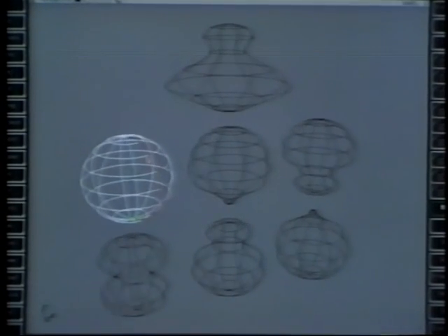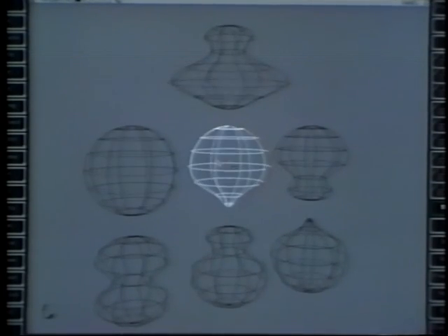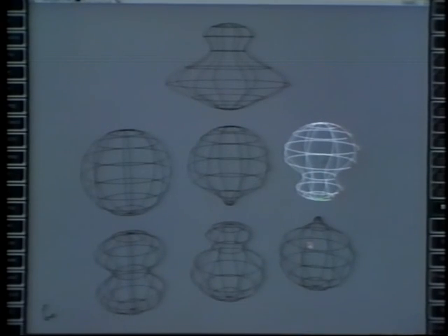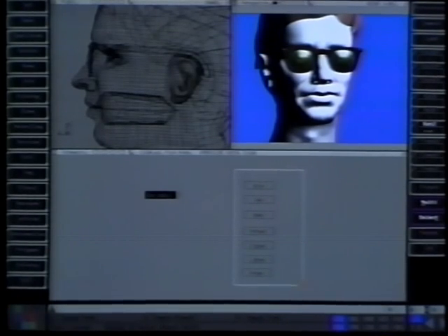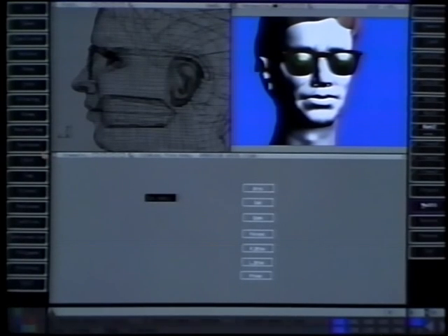It was okay for me to demonstrate Select Key Shape by laying out all the target shapes in different places on the screen, because the shapes in the shape list only record the position of each point relative to the object's center. In a real production, however, you probably will need to move each object center as a part of the modeling process, so when I model a set of facial key poses, I leave them in the same position in space and hide the ones I don't want to see.